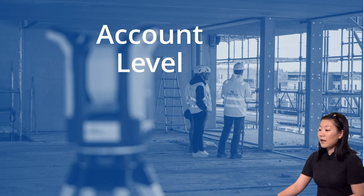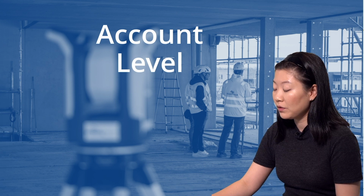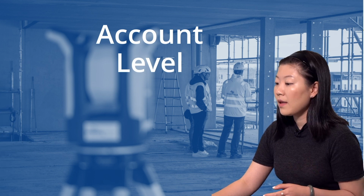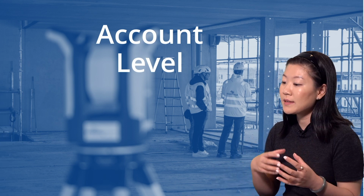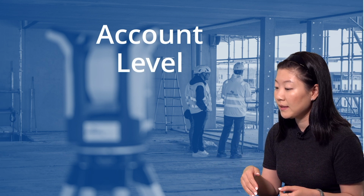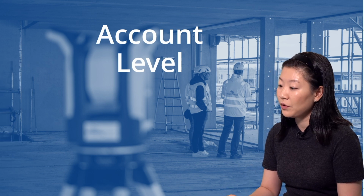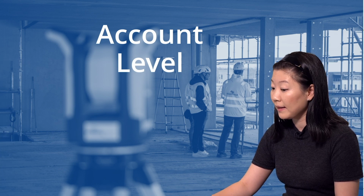Okay. Before we move further to the workflow at the construction phase, I want to talk a little bit about account level. Account level is a level above the project level. For example, BuildingPoint has an account, and it owns a certain amount of licenses in this account, and we can create projects under this account. Today, I will talk a little bit about two functions at the account level. One is data table presets, and one is property set libraries.